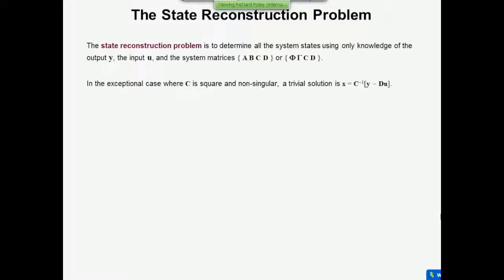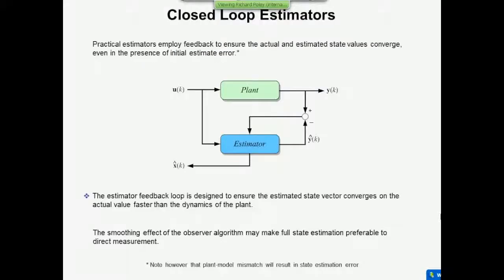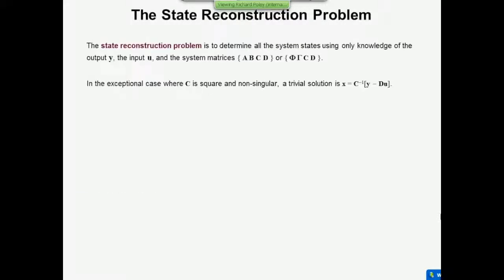State reconstruction problem then, just to ring fence what faces us, is to determine all the system states, that's the full state vector x of t, using y and u, because those are the two things that you can get hold of, y and u, and the knowledge of the state matrices, which you hope is correct.